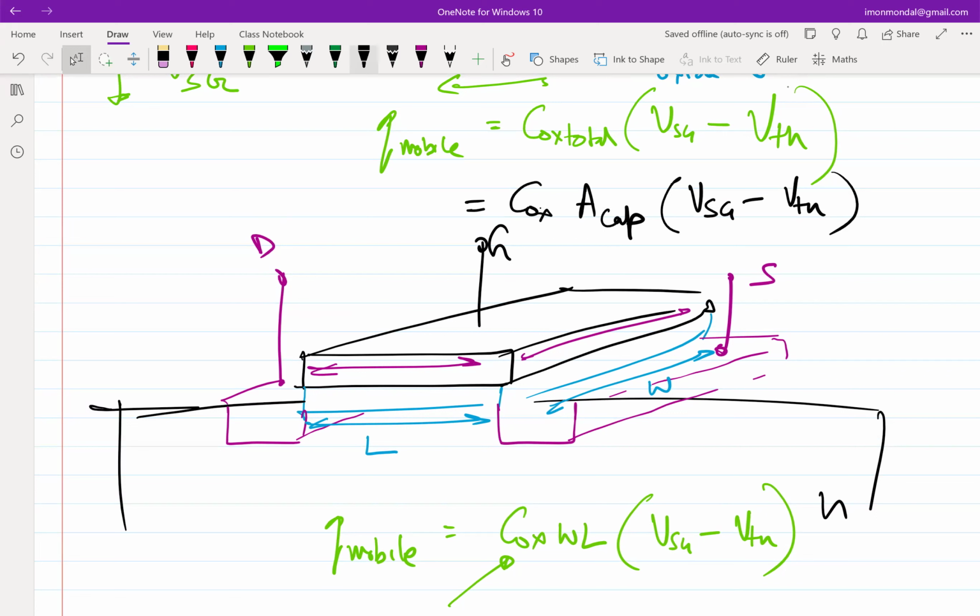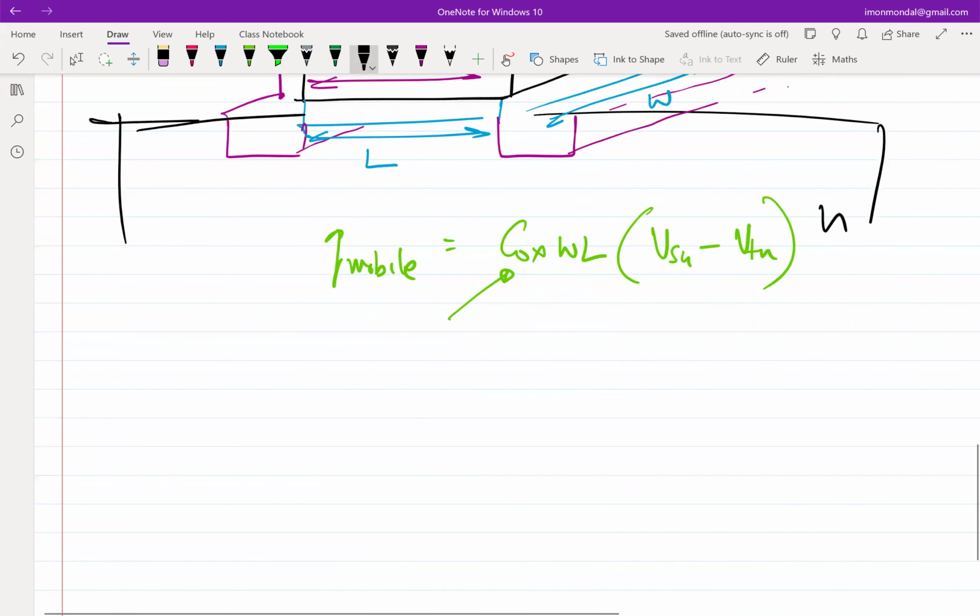Okay. So now that we have carrier concentration, we have charges, right? We have mobile charges in the channel. We can simply now say that forget about the gate, because the purpose of the gate is done. I've got the mobile holes concentration. Now, if I apply a voltage between the source and the drain, all I need to figure out is what will be the current. So it's now back to a two-dimension, or rather one-dimension